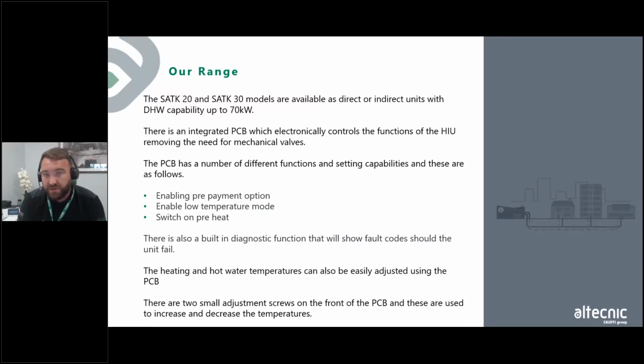We've also got a preheat function, and what the preheat function is for domestic users: if your HIU is the furthest one away from the energy center, when you run your tap there is a potential that it's going to take you a long time to get your hot water, because you've got to draw it through the ambient losses through the system. All the preheat does is just keep the plate heat exchanger warm, so the electronic valve will just pulse open and close to make sure that the plate stays hot at any one time.